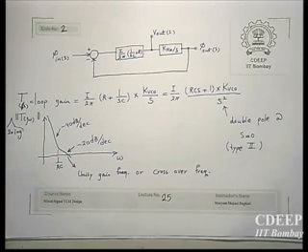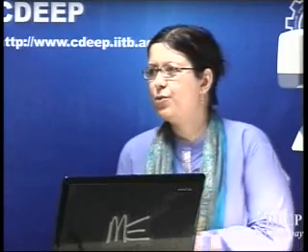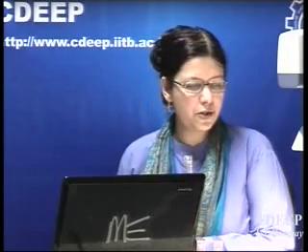So you have almost a constant frequency at the input, and the loop settles in such a way that you don't have any input to the VCO. The charge pump doesn't receive any signal. This is my perception, and if it is a filter, the filter still doesn't receive any information because the phase difference is 0. Otherwise, this loop should not remain.